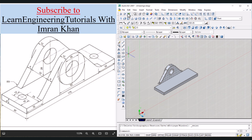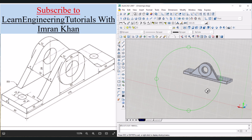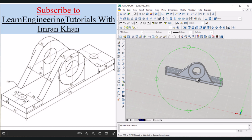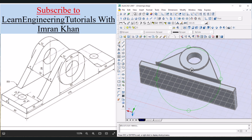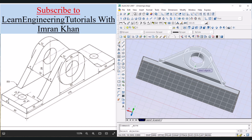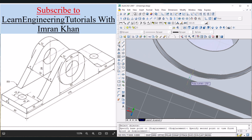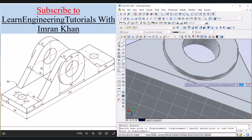Now use orbit to visualize this object and place it at its correct position. Now click on this move icon, select this object, press enter. Now click on this midpoint of this edge and place it over midpoint of this edge.